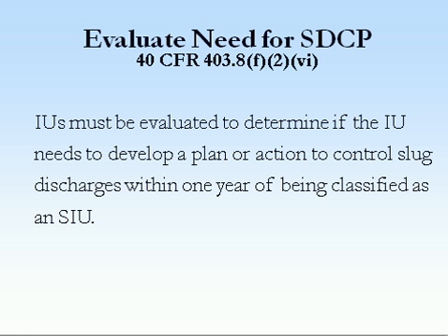Any user you've had for more than a year now should have already been evaluated for a slug discharge control plan. And not only should they have been evaluated, but you should have documented that you did the evaluation. The slug discharge, we mentioned this before, but the definition is any discharge of a non-routine episodic nature, including but not limited to an accidental spill or non-customary batch discharge, which has reasonable potential to cause problems at the POTW.